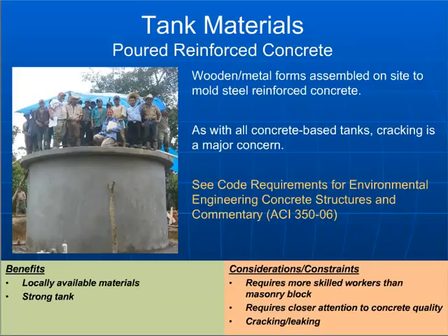The other consideration too with these is, since they don't tend to be very thick, making sure that you've got adequate provisions for live loads on the roof. You don't want somebody to be walking on top of this thing and falling through because the live loads on the roof aren't considered, so that's important.